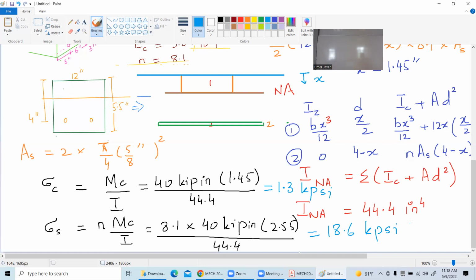I'm trying to say, don't think like that. I just removed those two rebars and I replaced them with lots and lots of concrete. Okay, but you're saying that there is concrete between the rebars as well. Yeah. You have to understand, this is an estimation of stresses, because you are trying to create a hypothetical section. So don't worry that the rebars also have concrete between them. Just relax, because this whole section that we have created is a hypothetical assumption anyways.